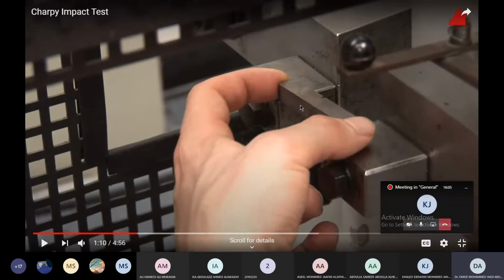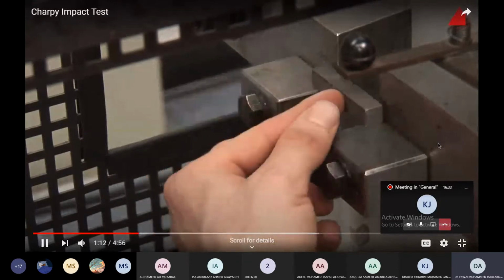You can see my mouse, right or not? Yes, we can see. Yes, the hammer comes from this side, so it comes from this side and hits. You see the notch is on the other side. Why do we do that? Because we make sure that this notch will open up when the hit is from this side. But if the notch is on the other side, of course, it's not going to open up and it might jam. The use of the notch will be obsolete. So let's continue, with a centering device.